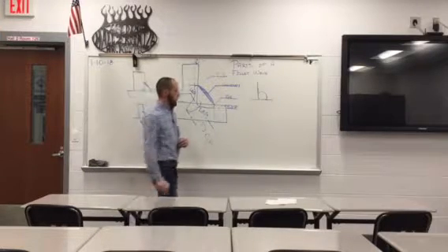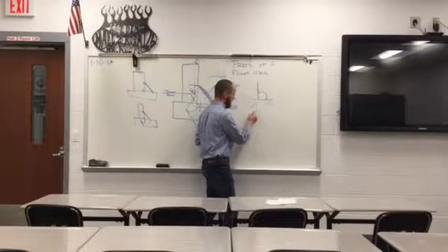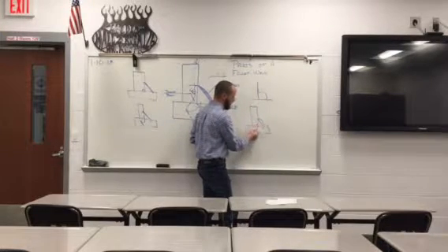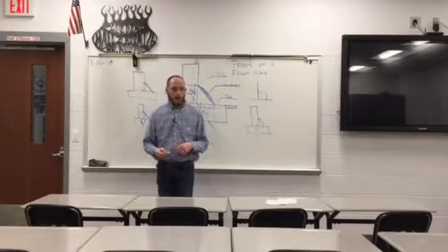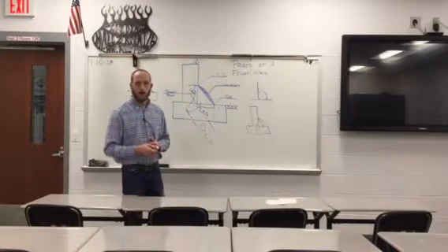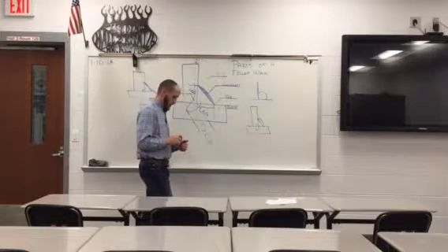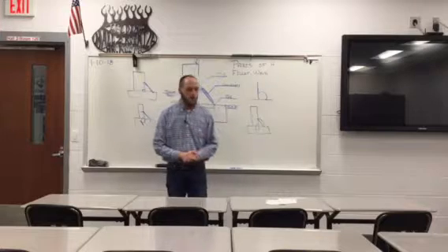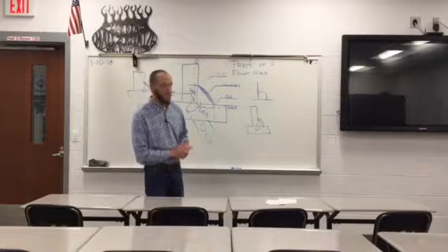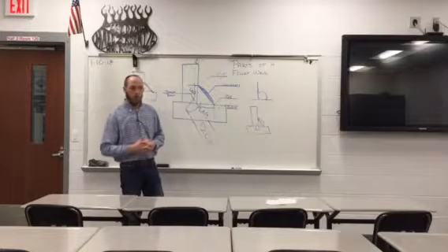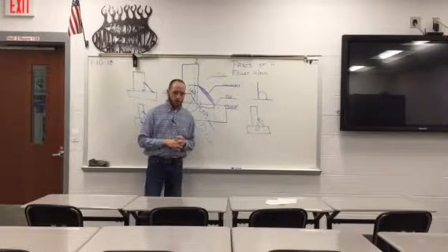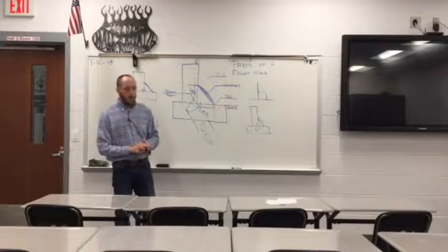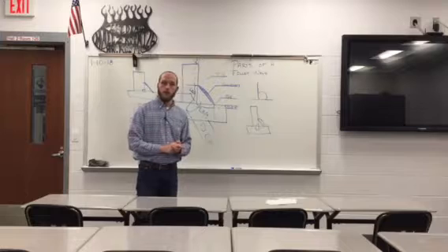Now, the last throat that we want to discuss today is our actual throat. That's pretty self-explanatory. It's actually what's there. That's measured from the face of the weld with weld convexity through the depth of penetration. That's most commonly used. 99% of welds have weld convexity, therefore it is measured from the face of the weld with weld convexity through the depth of penetration. And these are all the most commonly referred to parts of a fillet weld that you will use in your everyday welding career.